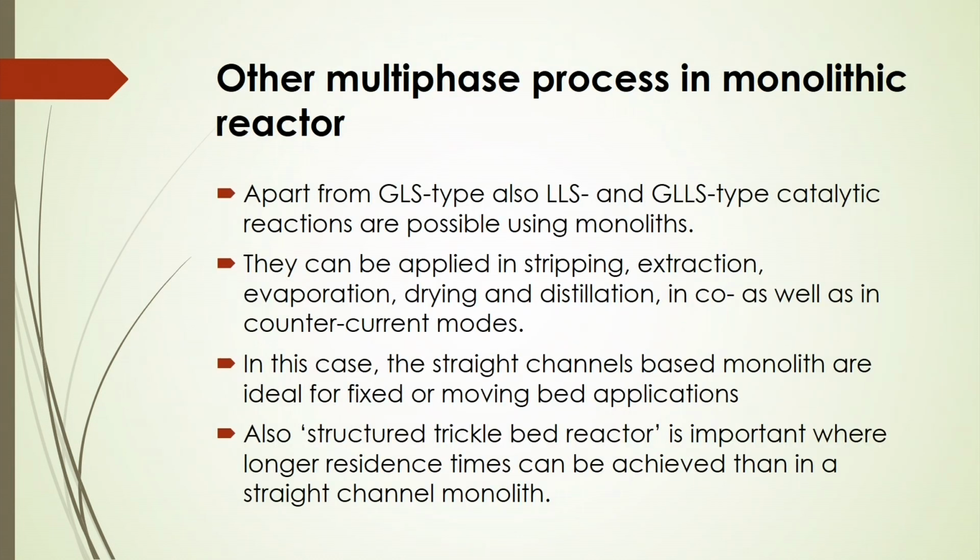Other multiphase processes in monolithic reactors, apart from the gas liquid solid type, also liquid liquid solid and gas liquid liquid solid type catalytic reactions are possible using monoliths. Of course, there are hydrodynamic aspects to be considered during the performance analysis of this monolithic reactor. They can be applied in stripping, extraction, evaporation, drying and distillation also.